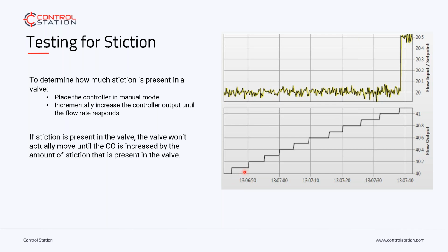If you don't know the dead time of your process, take a quick walk out to it and look at the distance between the valve and the instrument, and do a rough back-of-the-hand calculation: it takes about 30 seconds, or it takes 3 seconds for that liquid to reach that instrument, and you'll then know roughly what it is.